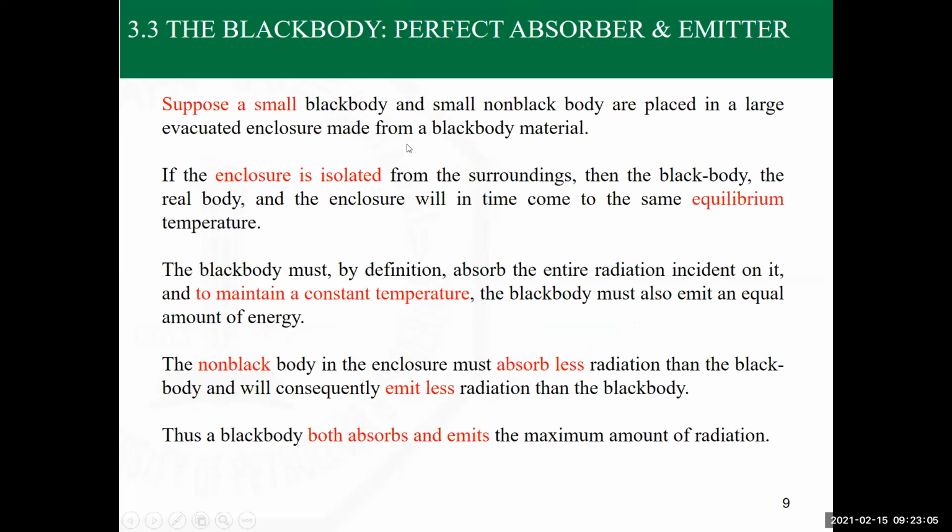Black body is not only a perfect absorber, I just mentioned a while ago that it's also a perfect emitter, which means that nobody can emit radiation higher than what a black body does. And we use this again for comparison between different surfaces, which is the same concept as talking about the Carnot cycle, or the effectiveness of a heat exchanger, or even a heat and mass exchanger for chemical engineers, that can be used for several applications.